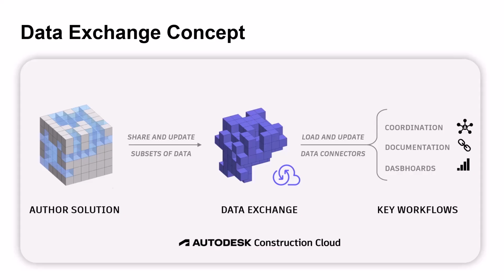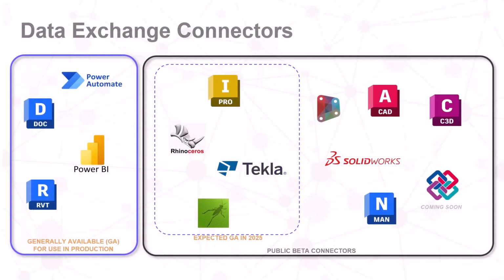And with data exchange, we can transfer only the relevant parts of the model. For example, just structural members or specific load cases to another analysis or detailing platform, and bring the results back. So this avoids exporting entire, for instance, IFC models unnecessarily and keeps the workflow efficient. For example, you can send data from Revit to another analysis software or to Tekla, or from Tekla back to Revit using the connectors. These connectors allow us to keep models in sync without overwriting everything, ensuring smooth collaboration.